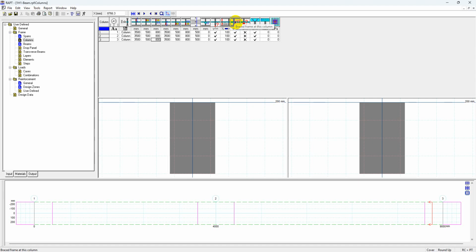Normally, engineers prefer to design buildings to be braced by a column or by a shear wall. So the engineer needs to decide whether to design this spanning beam to the column as a braced structure or unbraced structure. For this example, we will consider it a braced structure.